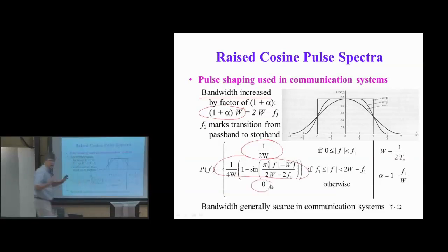Now remember, this is the ideal case, two-sided in time. In practice, we're going to truncate, so we will see energy in the stop band, or some non-zero values in the stop band. How does this look in terms of a picture? Well, it should look familiar. So the rectangular case, the ideal when alpha is 0, nice rectangular pulse.